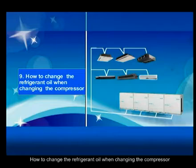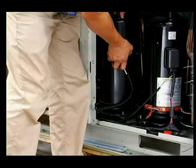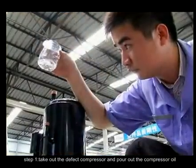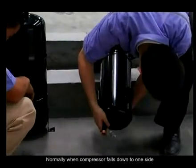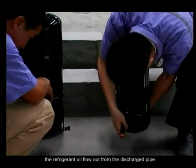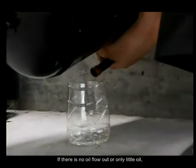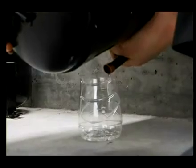How to change the refrigerant oil when changing the compressor. Step 1. Take out the defective compressor and pour out the compressor oil. Check the oil volume and quality. Normally, when the compressor is tilted to the other side, the refrigerant oil flows out from the discharge pipe. If no oil or only a little oil flows out, that means the compressor lacks oil.